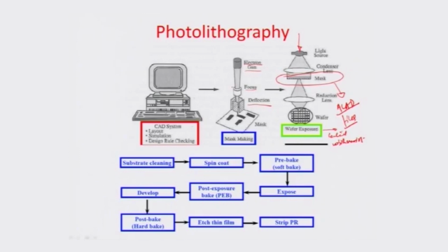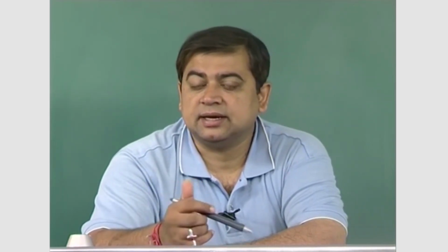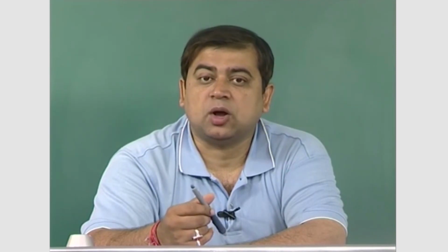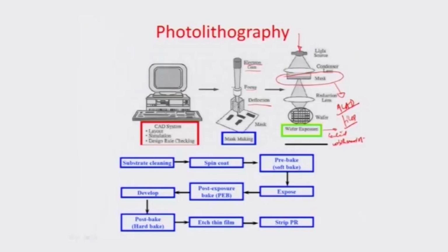You can get a printed transparency mask, where there is a Kodak Mylar film which you can print at a high resolution of about 5000 dpi, dots per inch, using a photo plotter, and the power of the CAD can again be used for printing different features and structures on the soft mask. Instead of using the hard mask, which is fabricated using a very complex e-beam scribing onto the surface, we use this soft mask, which can imprint or serve the same purpose.